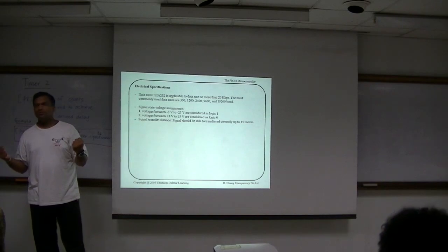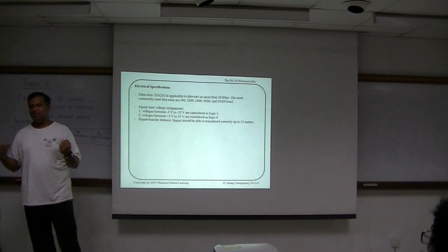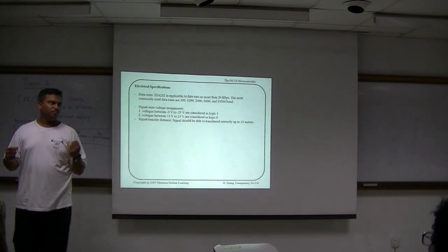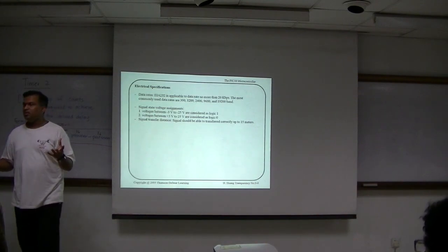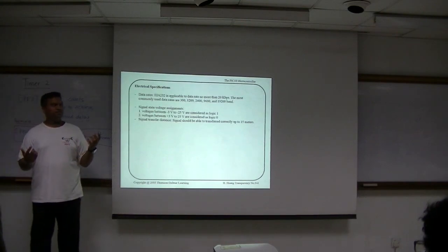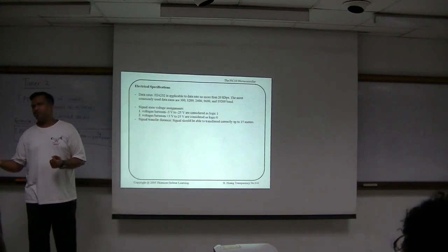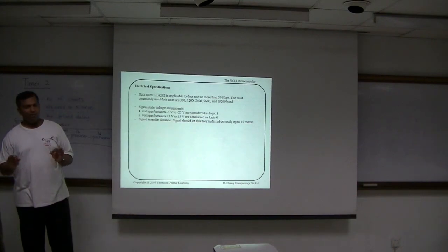It won't work. Since it's not a synchronized speed, you may have loss of data. Likewise, when you send something too fast but you're capturing it slow, you definitely have loss of data. So we want to make the speed synchronized. If you choose 9,600 here, here also should be 9,600. Simple concept.